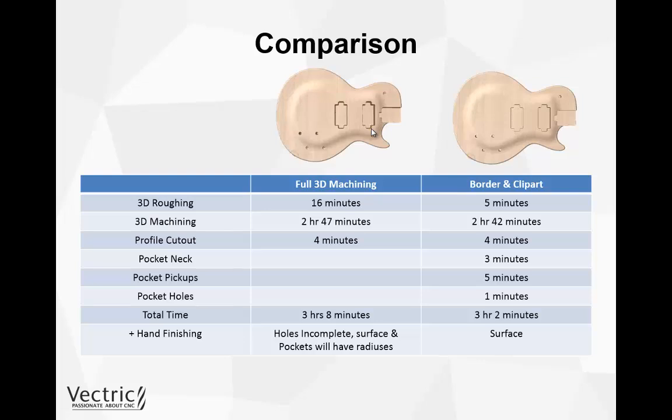So there are a lot of benefits to machining 3D more efficiently using vector boundaries and then using 2D and 2.5D toolpaths. In the Rose and Crown demonstration, it was quite obvious to see how much time we can save machining with that demo.